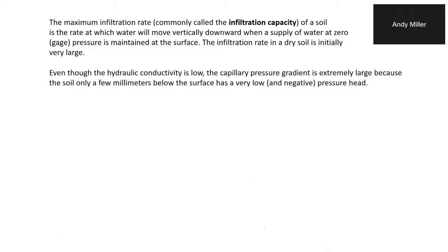Pores filled with air. Some of the pores are filled with air. Which pores are filled with air? The large ones, the bigger ones, right? Those drain first, leaving the water in the finer pores, sometimes with no direct path to connect to other finer pores. So it's much harder for water to move around in an unsaturated soil, particularly if it's confined to the smaller pores, which naturally have slower rates of transport, right? So that's going to be the case, that the hydraulic conductivity will be low in the unsaturated zone in a dry soil.